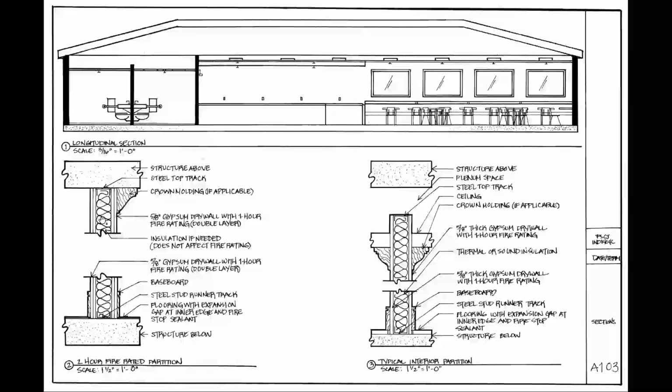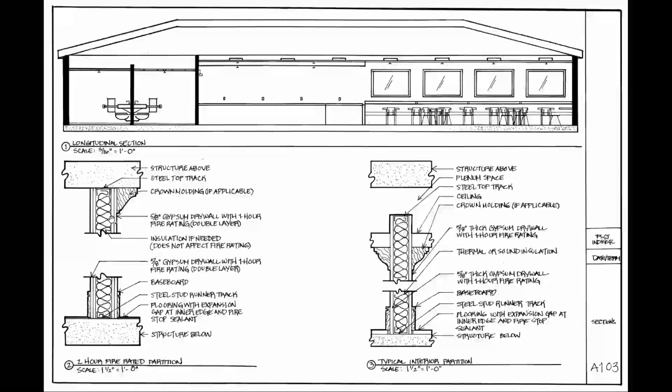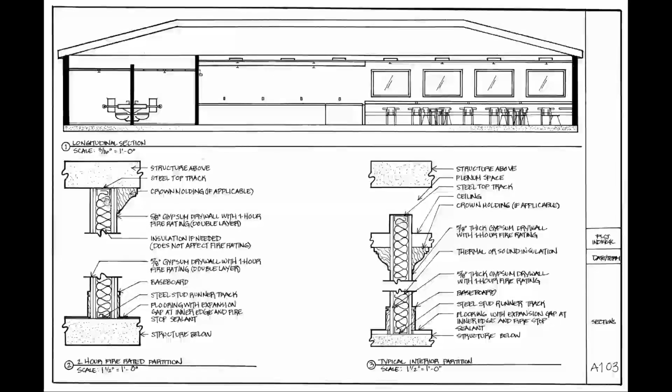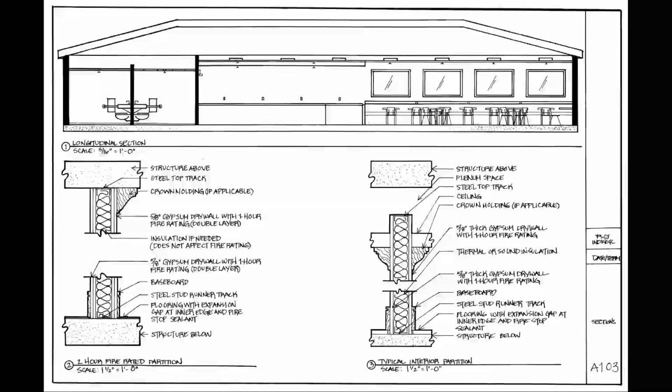Okay, inside the wall, behind the 2 layers of drywall, there's this insulation. And that's how we draw it. It's just a squiggly line that runs all the way down. And that's that pink insulation, or it can be blue insulation, but it doesn't have any fire protection rating. It's really just to separate for acoustics or thermal insulation. So if you want to insulate a space so it's not transferring noise or heat, that's what we use insulation for. It has no fire rating in this case.